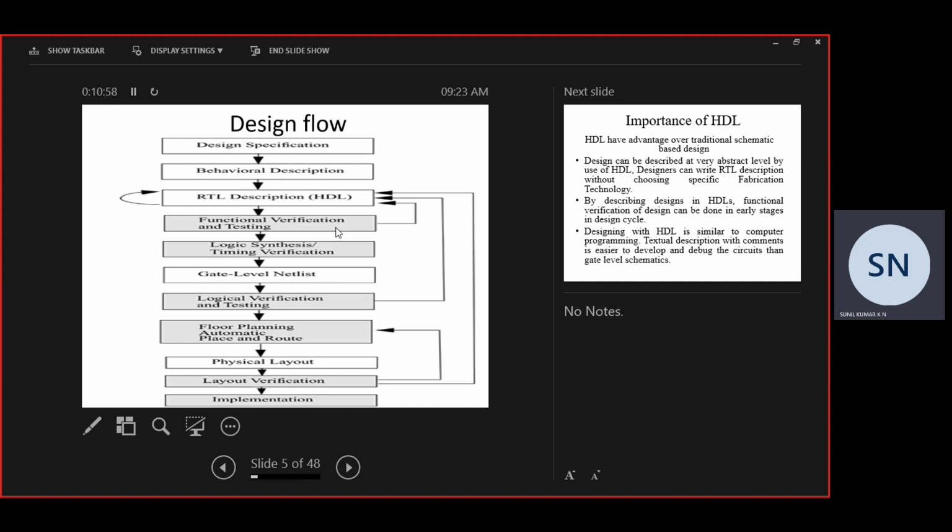Then next we see whether it can be realized, and how we can go about it. We can realize that circuit using a truth table, and all the supporting things, we are going to learn. That means the full adder concept. We have to see A, B, C: for 000, what is the output? You should get 00. That is what you write in the truth table.